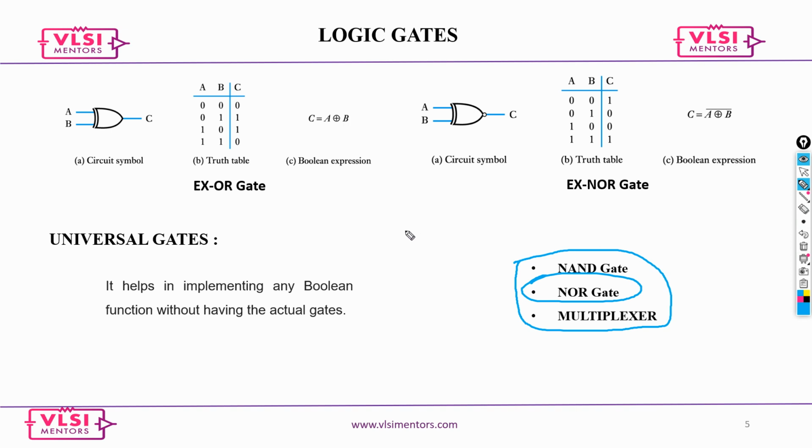The term that we use for all this is something called functional ECO. Just write it down. What is the meaning of functional ECO? That is the term that we use. Universal gates are used as spare cells, and we implement functional ECOs using those spare cells when we are very close to tape out. Okay, moving on.